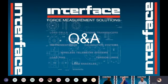Is it possible, or has someone successfully connected a 3-axis unit to an Arduino? Yes, it is possible. Especially the 3-axis, it's just like 3 load cells. So if you can connect a single load cell to an Arduino, you can connect a 3-axis.